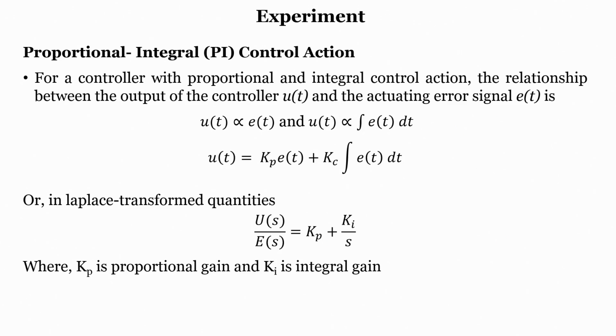So, another way of implementing a system is by using proportional and integral. So, if you understand, we are adding one more component into the system, which is nothing but integration. So, what is an advantage of having an integration? We have seen that with respect to the proportional controller, the output will change proportionately based upon the error input. If the error is higher, it will always be higher. If the error is lower, the output will also be lower. But if the error is constant, as long as the error is constant, it will always maintain the constant, right.